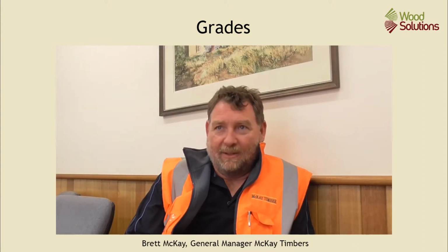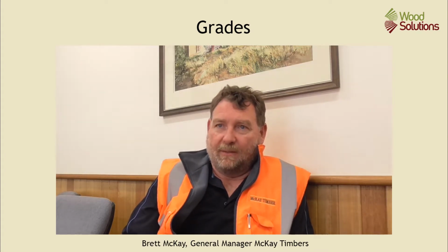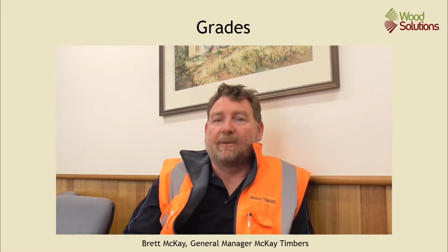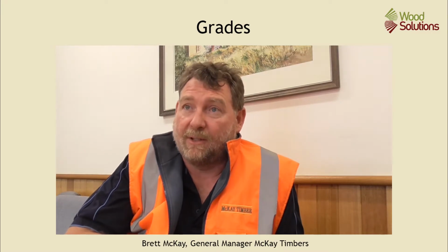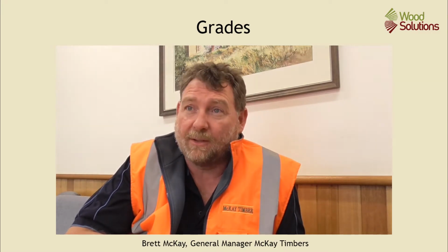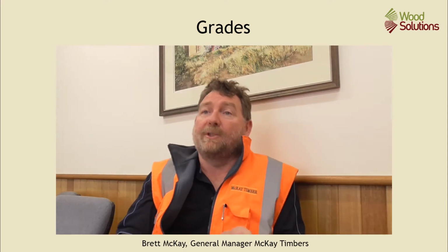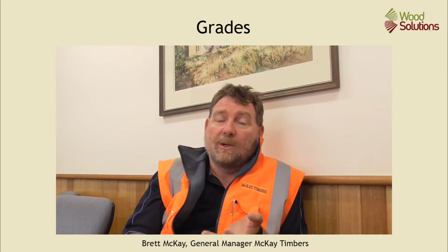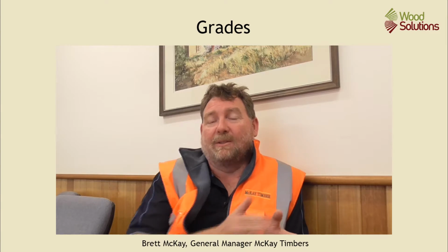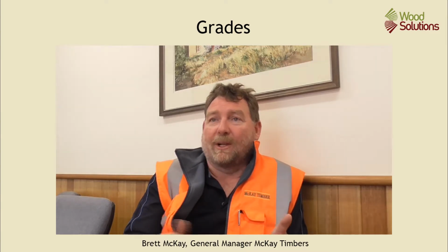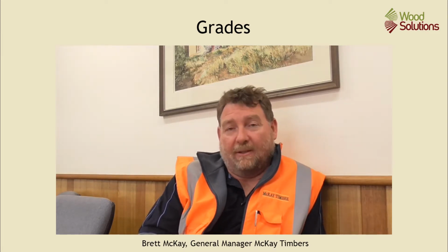We grade our timber because we're trying to get a full range of products out of the timber. So we're grading it for structural, for framing, for all for structure. For F17, we also grade for appearance for joinery products. We also are grading for feature for the new furniture markets that are out there. So we're grading the full spectrum to get the best value out of that board and put it into the appropriate product. So we grade our timber for various reasons, starting right back in the log form.